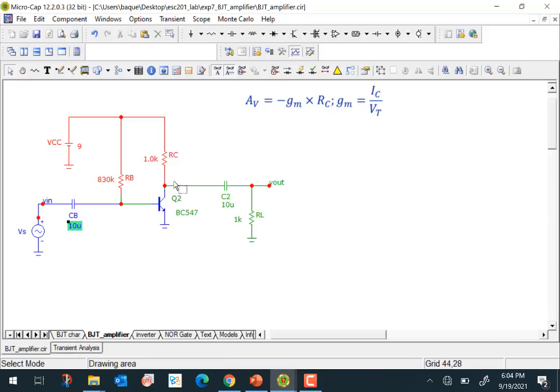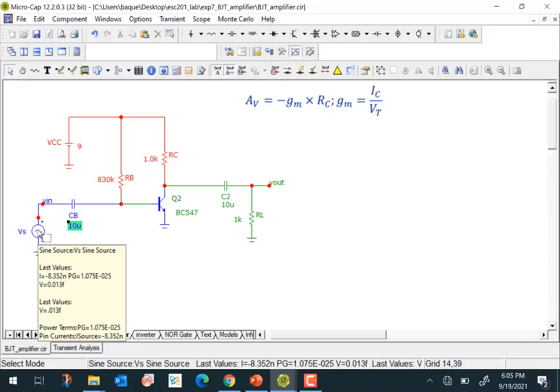The relationship between collector current and base current is linear, but the base current itself is non-linearly related to this input voltage. The changes in collector current will cause a change in the output voltage. That sinusoidal collector current would flow through a parallel combination of RC and RL, and cause a voltage here. So the relationship between the collector current and this voltage is non-linear.